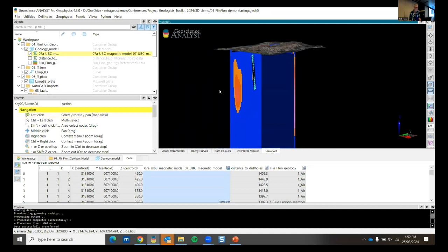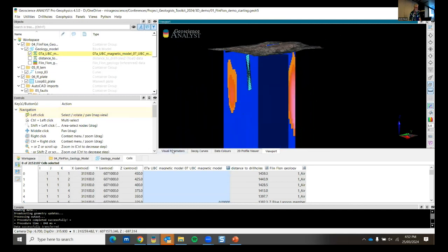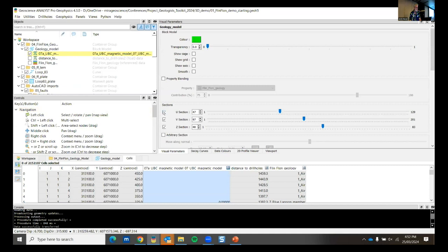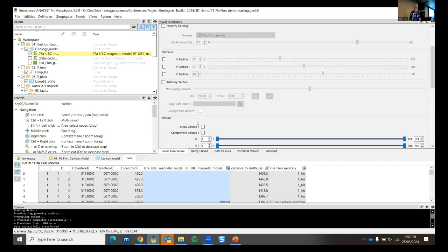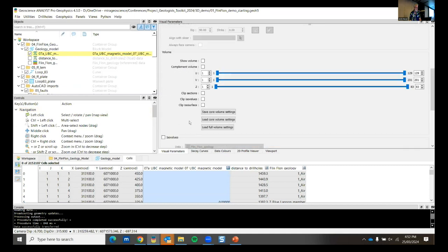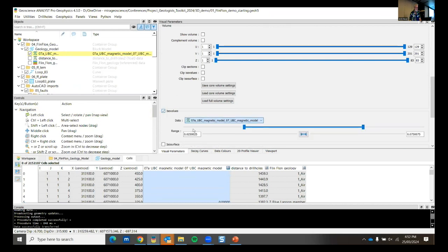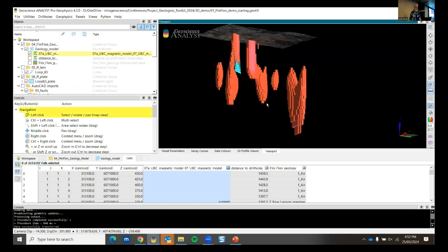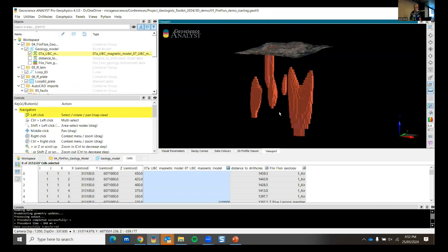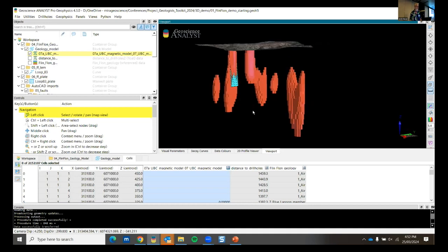And then I'm going to go from here. Instead of visualizing this as just slices, we can do things like calculate isosurfaces and show ISO values and things like that. I'll just show a susceptibility ISO value, and I think that one's a good one. It's just showing the areas of high magnetic susceptibility in the model, and they're shown here, right? So it's like an isosurface, just enclosing all the material of a certain magnetic susceptibility and above.